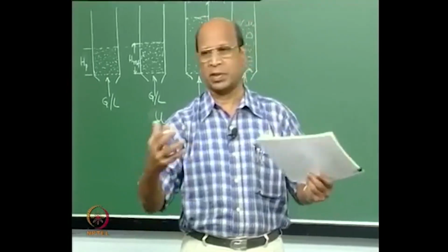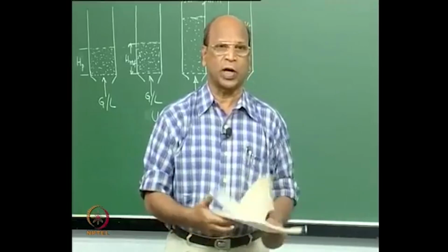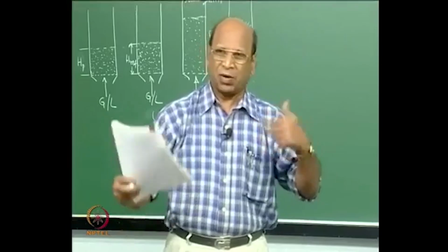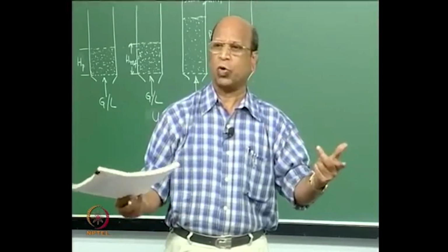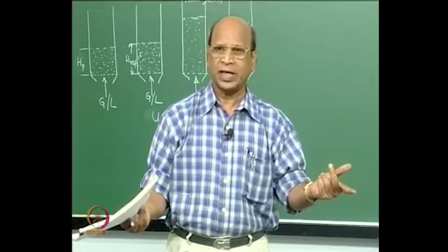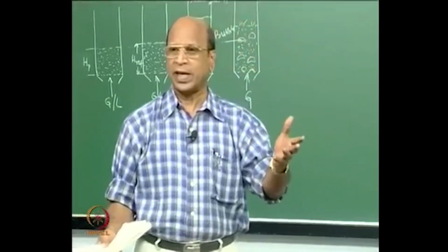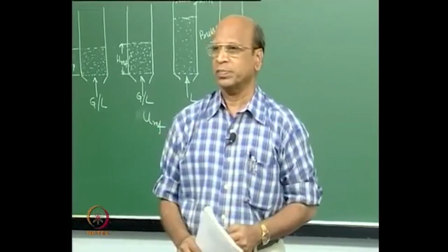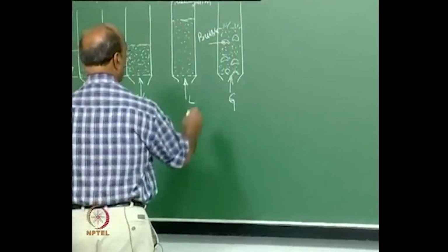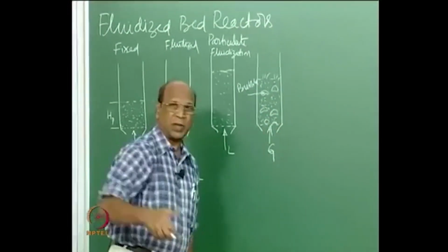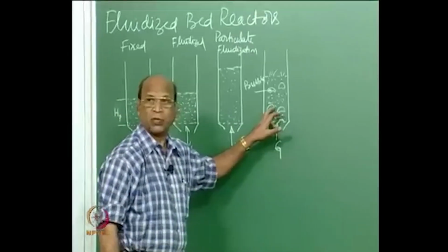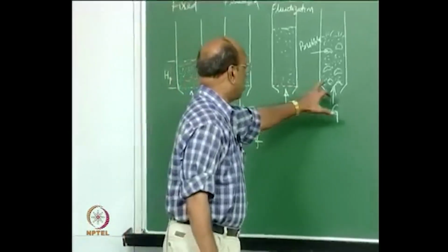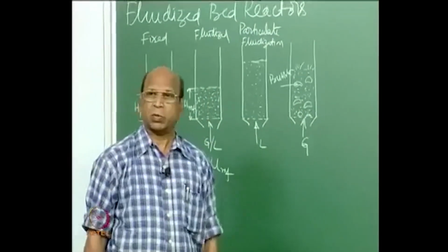Many people say that no, some other gas is going this way, that way, still fighting is going on, but still majority of the gas goes only in the form of bubbles, and our imagination is that there is no other way for the gas to go. So, either it has to support the solids and go, otherwise it has to go as bubbles. So, that is the reason why you have here a kind of aggregative fluidization where it is not uniform, because where the bubbles form, where the bubbles break, you cannot say. In fact, when you have this situation, you can do that experiment in your house also.